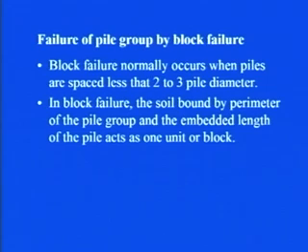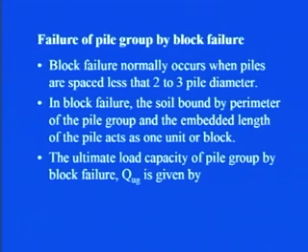Let us say you have 100 piles together in that particular group. What will happen? The area covered by those 100 piles will behave as if there is only one pile of that larger size, and the length will be the total overall length of the pile. So, that total thing will behave as one particular unit or block.